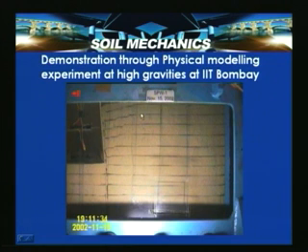Then the wall yielded, rotated about a certain point here, and moved away from the backfill. In the process, you can see the development of these lines, which are nothing but sand marker lines. These lines cut into a number of planes, and these planes indicate the rupture planes which developed, which we discussed in the previous case.